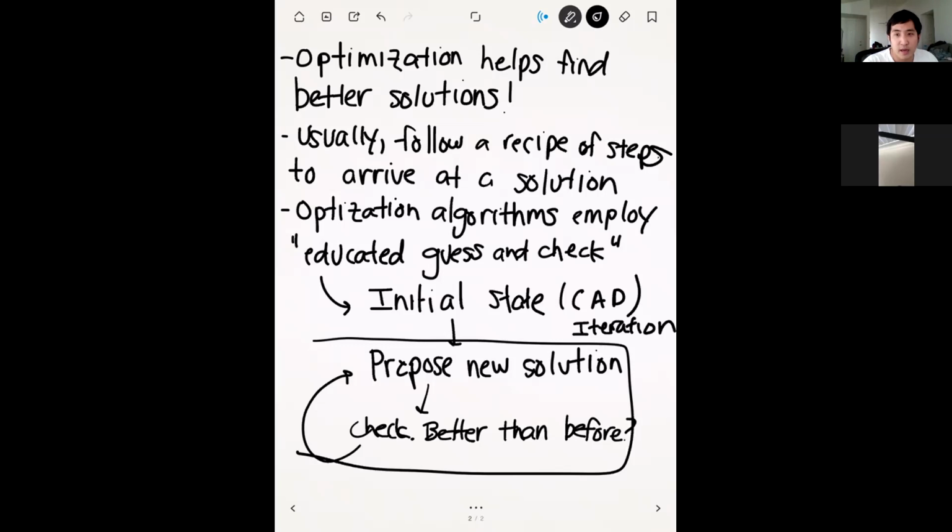Generative design, I've not heard that term before, but I'll let you decide if it's the same thing. What's going to result from ANSYS is an optimized model, but it's going to be pretty rough around the edges, because this is basically being done by a computer with no knowledge of how easy or not this is going to be to manufacture. So what I'm going to recommend is that you take the general result that you see and use it as information to modify your CAD model manually. It'll make sense once we get there.